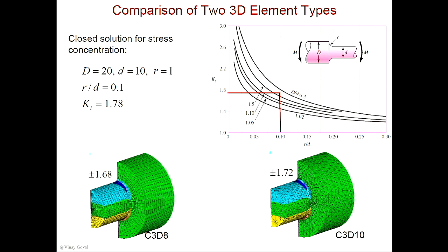I may show you when we cover fracture. I wrote a user element that basically models fracture, right? But I use shape functions, I use Gaussian quadrature, I use all this stuff we're talking about. There's no difference. The only thing I did different in my code was the constitutive law. I was trying to look at fractures, so I came up with springs that break, and the constitutive law was different. But otherwise, isn't the formulation about the same over and over and over?